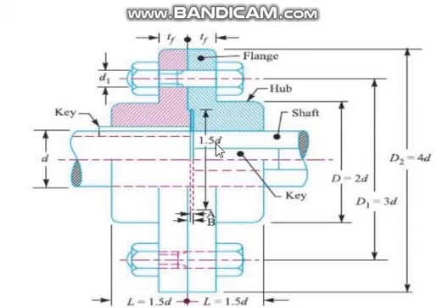You see, even here in the machine drawing there are some mistakes. Up to the center line it is not cut, so this line should have come up to this place. This line also should come up to here. These three lines should have come up to here.